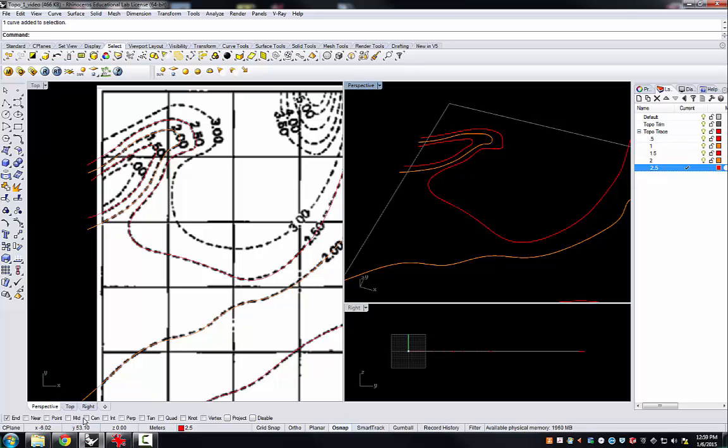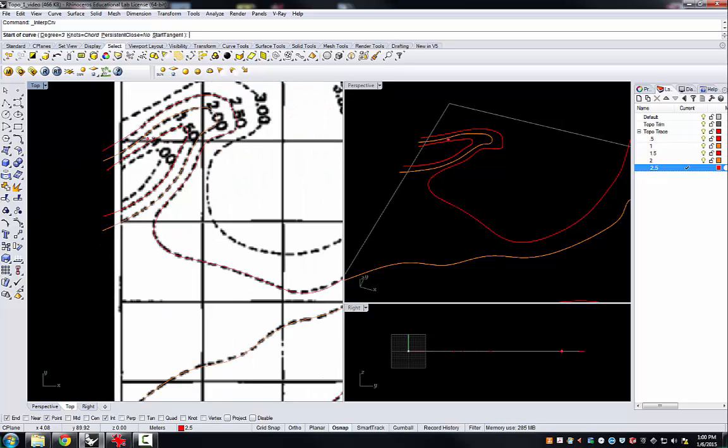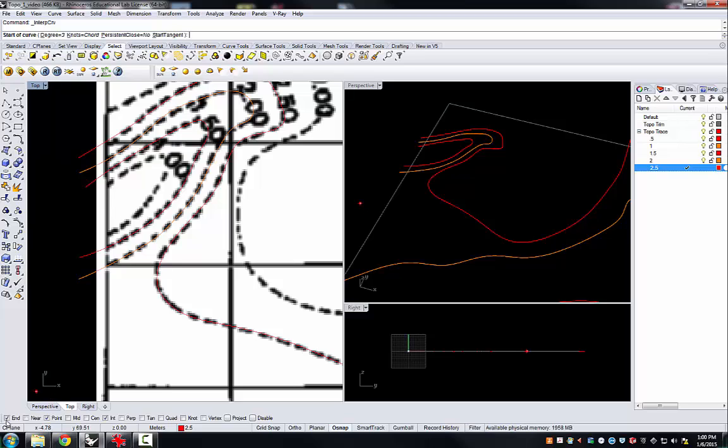And when we were inputting things before, I randomly had on a few object snaps, O snaps. I had point and intersection. And if you keep those on and try to make your curve in an area that has a lot of other curves or where there's not much space between them, you'll see that it starts to stick to the other curve, to the intersection, to the end or whatnot, in ways that I don't want it to do. I want to be able to start free of that and not have my points get sticky. So to do that, I'm just going to disable these O snaps.